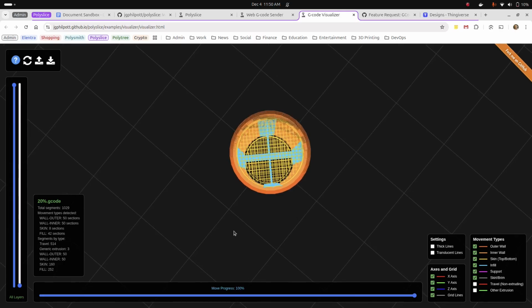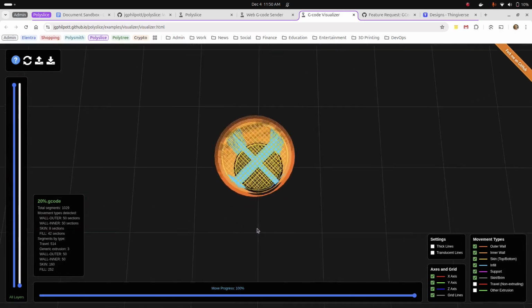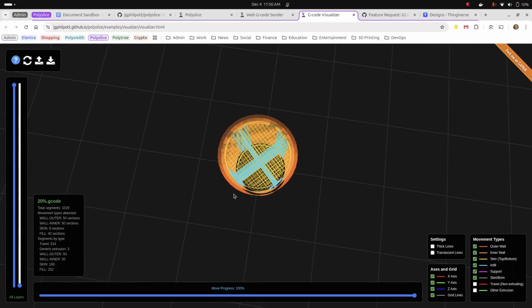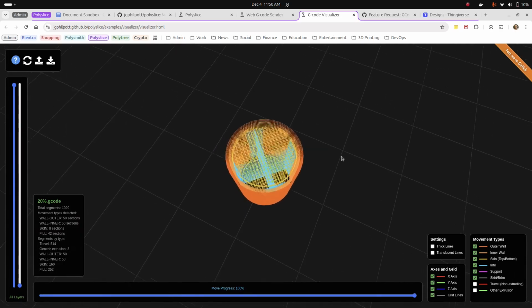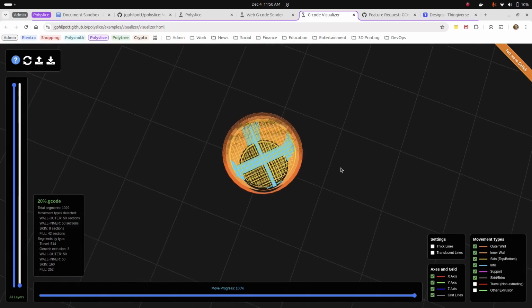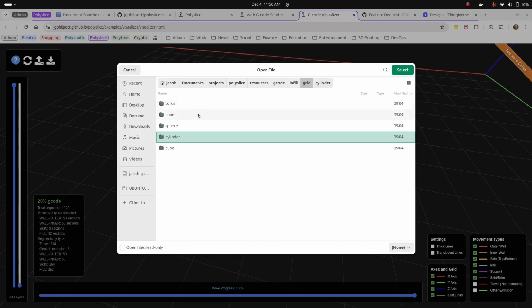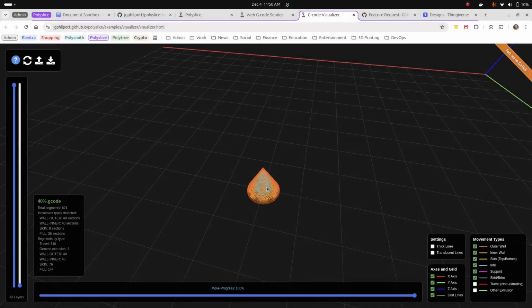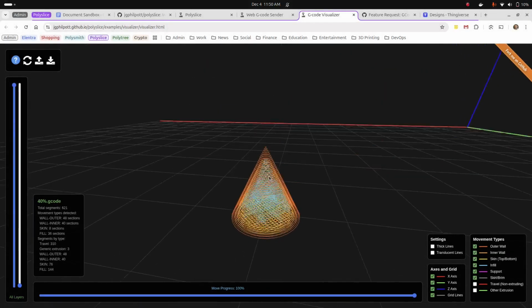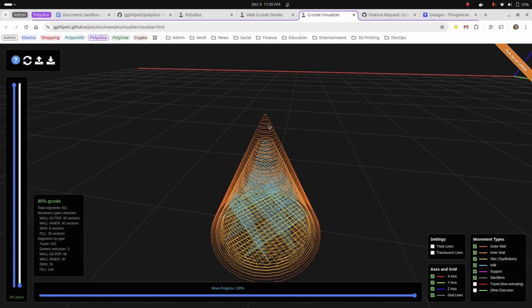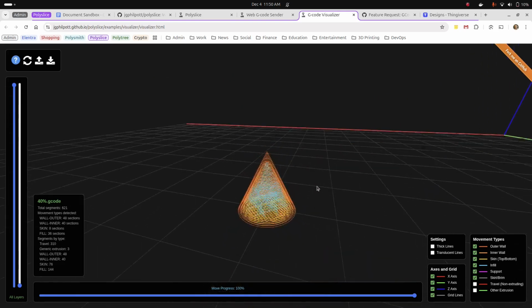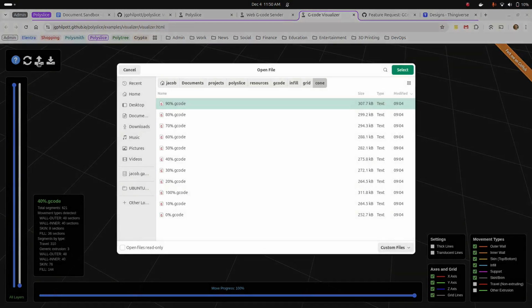So this had another set of challenges to it, figuring out how to clip the path so that it fits within the round shape of the cylinder only and doesn't extend beyond it. And then from a cylinder, I moved on to a cone. This had another set of challenges, determining if the area at the top was too small to try and generate infill. At first it was generating infill and it was having all kinds of problems. So again, more challenges with each new geometry. The slicer was becoming better and better.